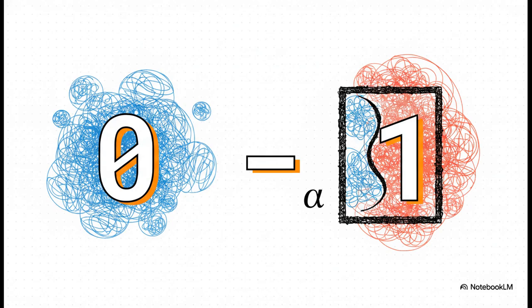So how does it actually track that boundary? It does this using a volume fraction, represented by the Greek letter alpha. It's quite simple, really. If a computational cell has an alpha of 0, it means it is entirely filled with the secondary fluid. If it's 1, it's entirely the primary fluid. But if the value is a fraction, somewhere in between 0 and 1, it means the interface between the two fluids passes right through that exact computational cell.